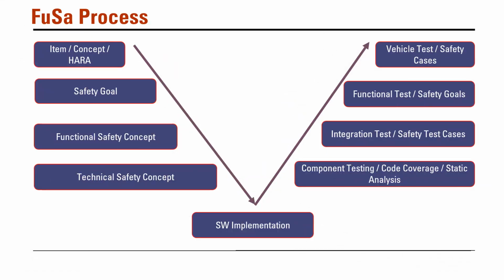In terms of process, I said the functional safety process, like a V-model. So here we can see the first item is HARA. Mainly it talks about hazard analysis and risk assessment, as we spoke before. And here we can detect different kinds of hazards from the concepts or items that have been defined from the basic requirements, and we perform risk analysis for these hazards.